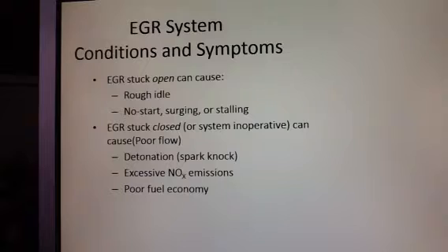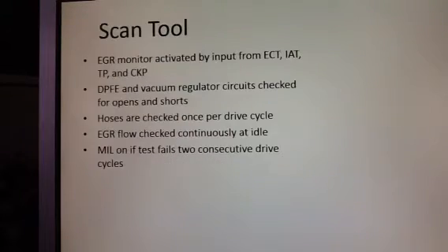With our EGR stuck closed or system inoperative, we can see poor flow on this. If it's either stuck closed or has very, very poor flow, we can have detonation or spark knock. We can see excessive oxides of nitrogen, or NOx emissions, and we can have poor fuel economy with this also.